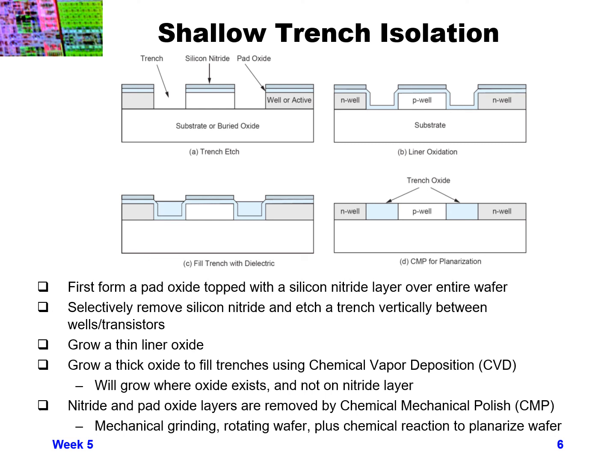And then we can also be etching the silicon, so we'll wind up doing a vertical trench etch in the areas where we want the trenches, and we'll etch that down till we get below the area where the P-wells and N-wells are ending, how deep they go into the silicon. So once we've done that, we can remove the patterned photoresist, and we'll have the trenches.